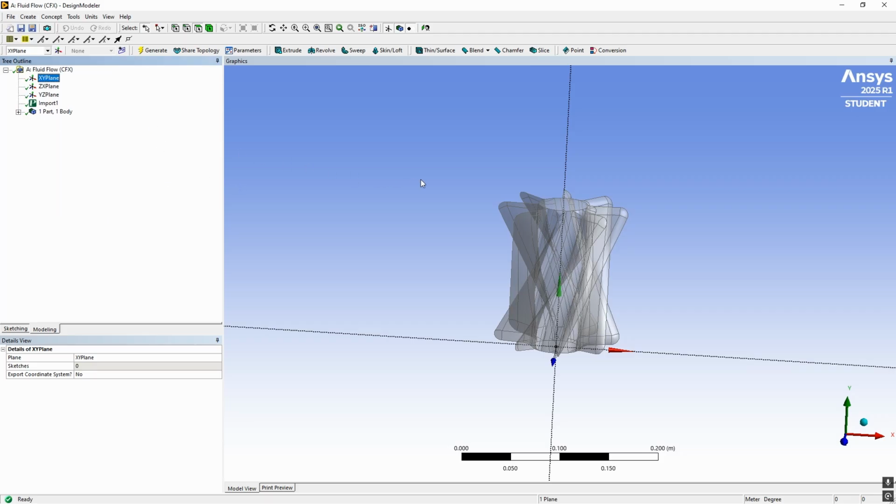The reason why we do this is, first of all, let's talk about CFX. Why do we need CFX? CFX is software that allows you to model turbo machinery, the rotating machinery, and the flow studies around rotating machineries better. You can also do these studies through Fluent, but if you do them through Fluent, you need to set up your mesh differently. Instead of changing the mesh type, we can generate it in CFX, and instead of messing with the mesh, we will be generating rotating domains and stationary domains. It might seem a bit complicated at first, but it's very simple.